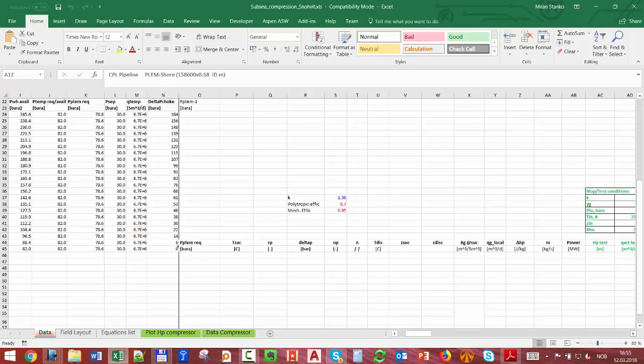Pressure ratio I calculate by making the intersection. Delta P, I'm going to assume a polytropic efficiency. That's something I'm giving you. We're going to use the same as Oscar. Polytropic exponent, I calculate the discharge temperature. I calculate these two sets to calculate the average. Remember, we need that in one equation. We need the local rate, right? To plot this plot.